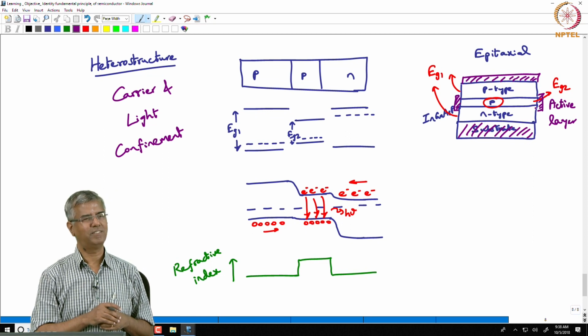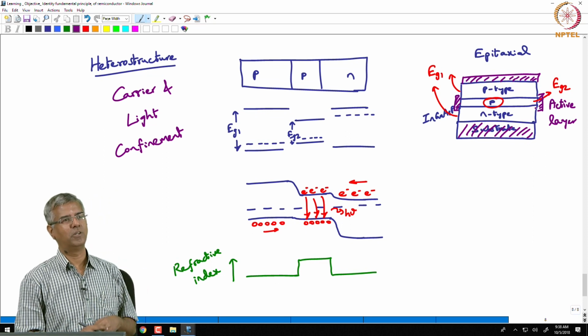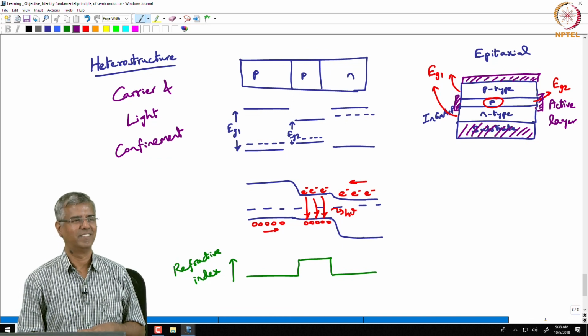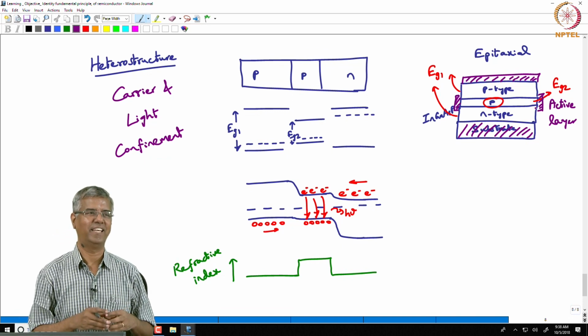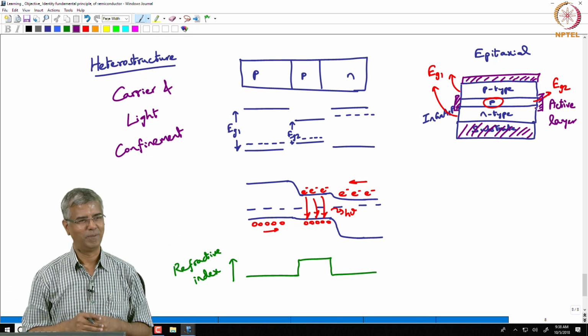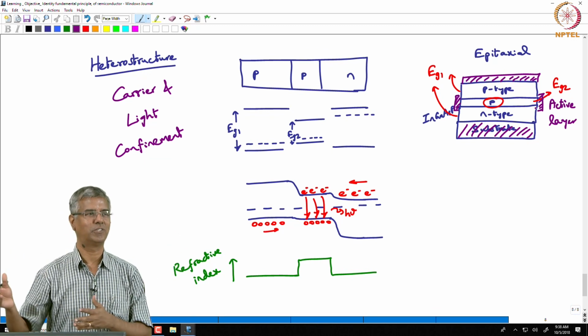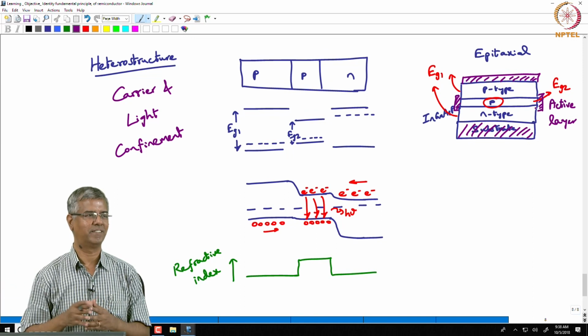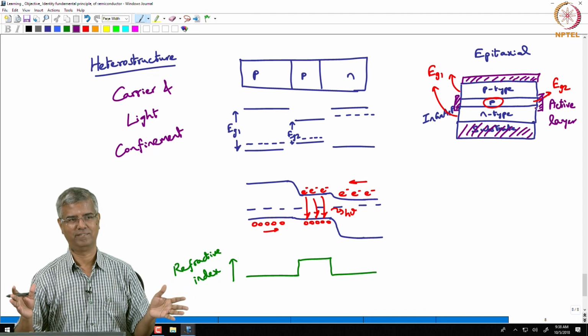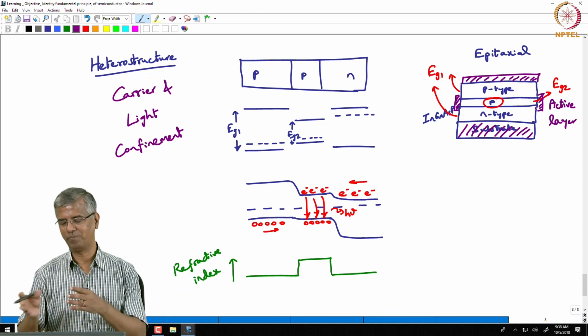That seems counterintuitive. You're talking about an optical surface and you want to make it rough, because rough essentially means light will scatter everywhere from that surface. But that's absolutely okay, because most LED applications require light to be scattered over a wide region. The more the better, right?